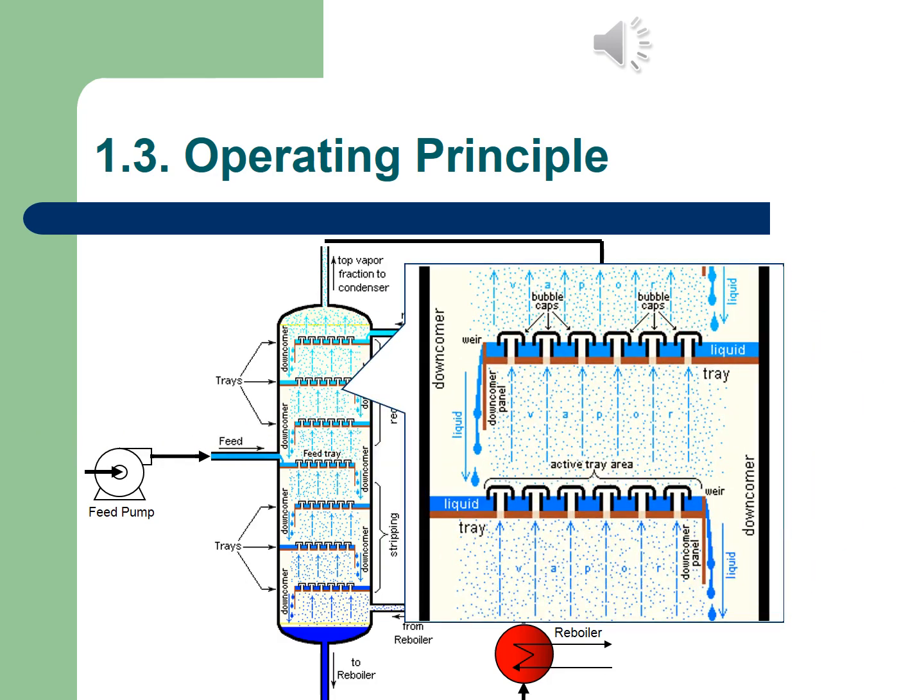Okay, this figure here is just to show you inside the column. Usually you have some trays, and those trays have bubble caps and so forth. That's just to cause further purification. So the vapor will rise up, it will cool down, and it can fall back again to the next level. Since this is a very large column, the temperature is going to differ a little bit inside the column at the different levels. And this is again to get a better purification in the system.